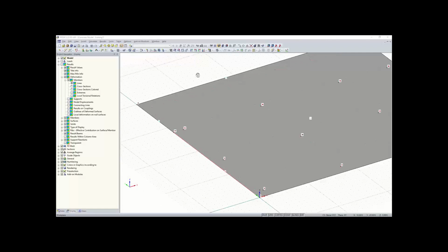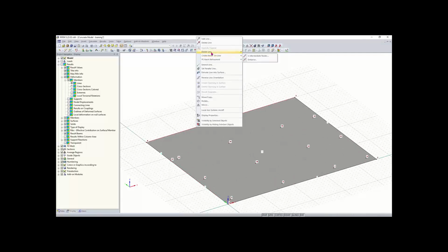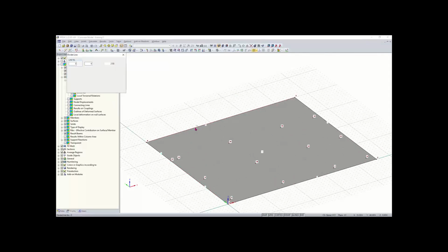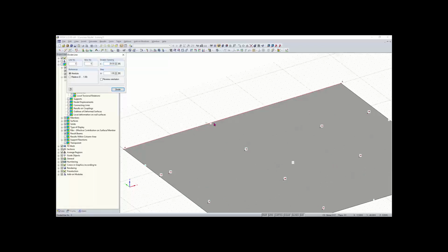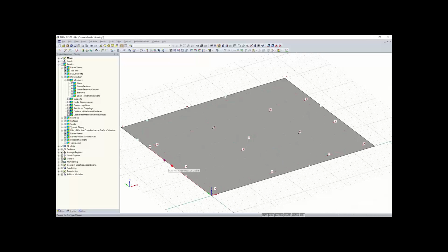And now we can do the same thing for this line up here at the top. I'm going to click on it, right click, and select divide line graphically. And maybe just to reiterate what graphically means, you can see I can just snap or place the node wherever I want on the line using my cursor. I'm going to place it right here. This is going to be 28 feet from the start. So I'll place that, and now you can see that we have 2 lines with the node placed at 28 feet from the start. And again, if you're confused about the orientation of your line, when you hover over your line, this red arrow tells you the direction.